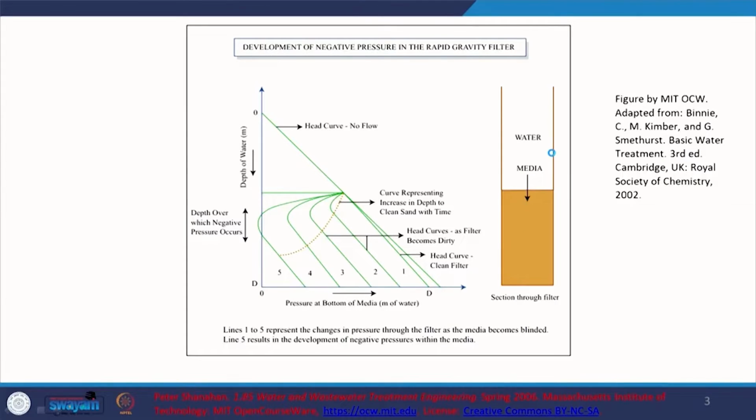So, one aspect is that if we do not look at the relevant performance and the relevant backwash, we can even have negative pressure being developed during rapid filtration. So, here we have this water out here. Water is at this level, right, and here just water above the media, right. This is what we typically have, and under this head water is filtered through this particular sand.